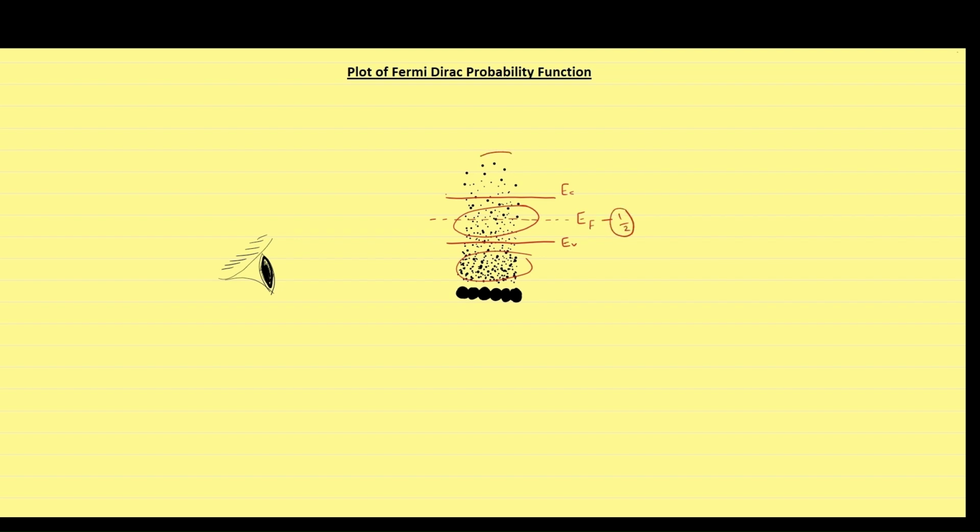Now, we will consider these topmost region electrons. These are the electrons which have absorbed sufficient energy to make transition to conduction band, and are considered free from the crystal's electrostatic force. When an external field is applied in the shown direction, then these electrons are the most mobile electrons that respond to the external electric field.